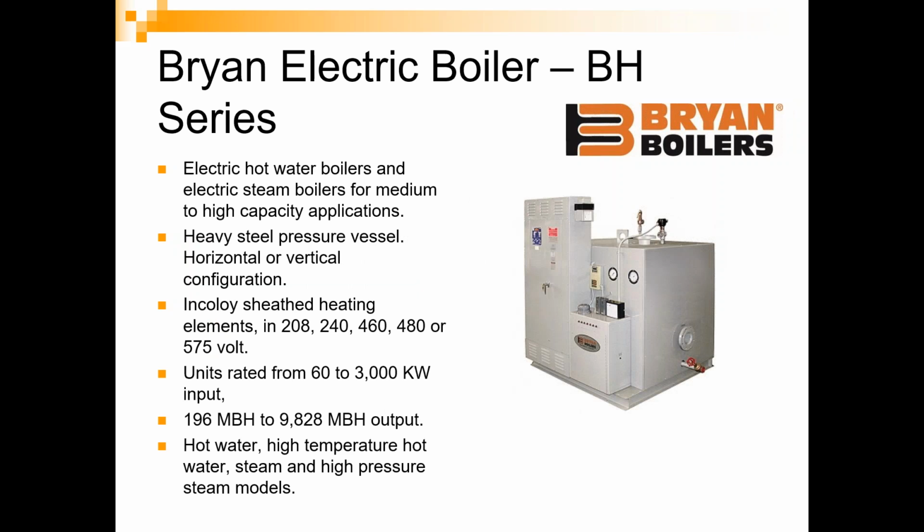But Bryan also makes electric boilers in the larger series, the BH series. These are available in 208, 240, 460, or 575. These units are rated anywhere from 60 kW all the way up to 3,000 kW, or 196 MBH all the way up to almost 10 million BTUs. And we're seeing some large electric boiler projects these days. These are available in hot water, high temp hot water, steam, both low and high pressure steam.